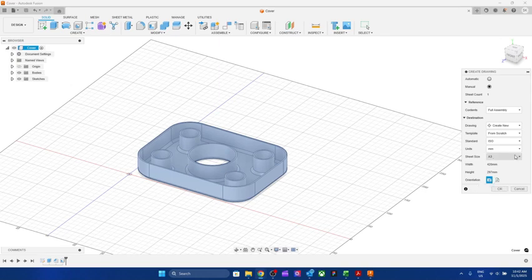But these are the standard parameters that you need to make sure. It's going to be A3 size. If you want to increase the size or decrease the size of the paper, you can do so. A3, A2. If you have a big product and it has a lot of parts, different parts, then the drawing sheet size will increase accordingly. Okay, ISO, create new drawing, and you simply select. If you want portrait, A4 or portrait or landscape. If you want A4, you can do so as well, and then click OK.